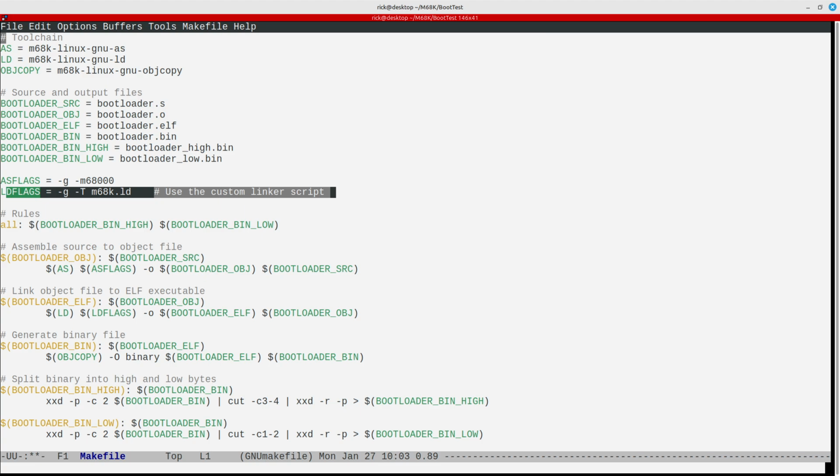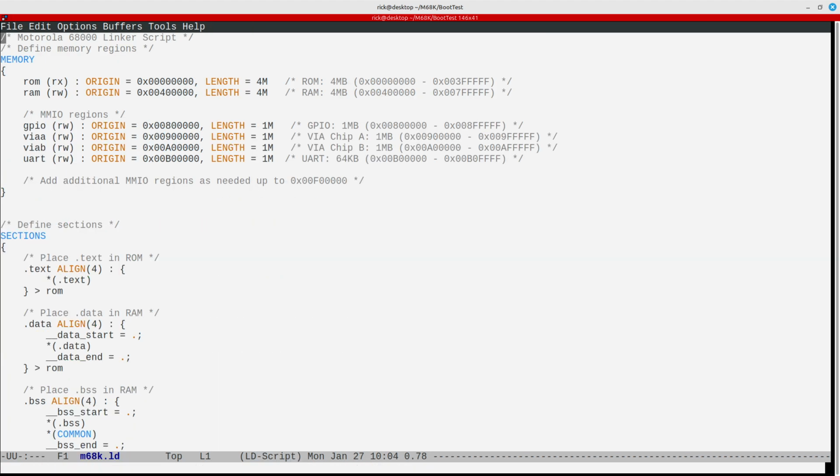For example, the .text in assembly might map to the ROM region, .data to the RAM region, .bss, which is uninitialized variables, go to RAM but start zeroed. So all of that is done, or can be done, with the linker script, like I've got here.